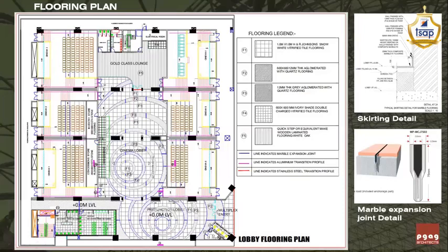Now first, as explained to you in the last slide, the floor finish of the particular area has to be written. Like if there are some levels inside your site, you are planning to have some upstand, or some level up than the 0.0 meter level as your finish level, then you are supposed to show that in the flooring plan itself. So all the levels should be clearly marked.